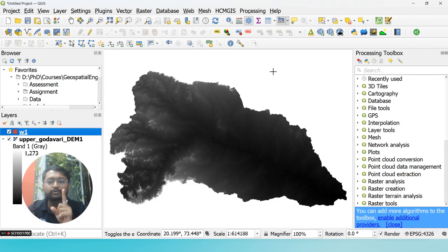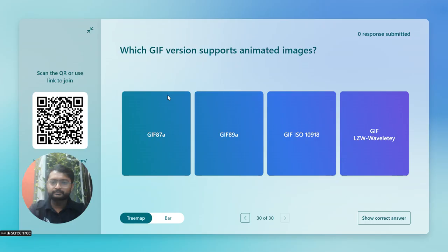So it will consider what kind of coordinate system you have. If you use it without the dollar sign, then it will always give the same area in the normal coordinate system, the planimetric area, without considering the projection system. And if you use the dollar sign, it will consider the coordinate system in which your data and units are. Okay. Yes, I understand. Thank you. Okay. Any other questions?